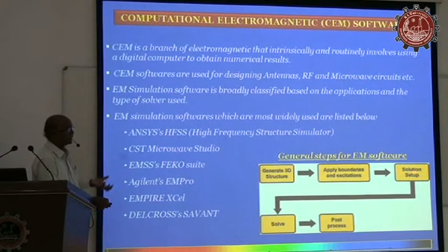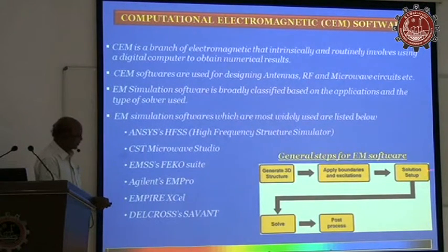Suppose, for the sake of speed, you set up the solution frequency at a low frequency or mid frequency, your high frequency results will suffer. So that is why we have to take the solution frequency at the highest frequency. Then the sweep: whether you want a discrete sweep or interpolating, and at what step you decide the frequency, then solve it. Then post processing. I have found that ANSYS HFSS has very good post processing features.